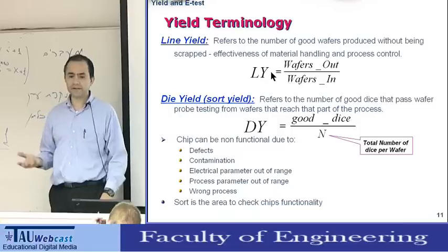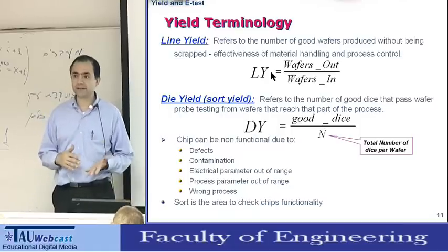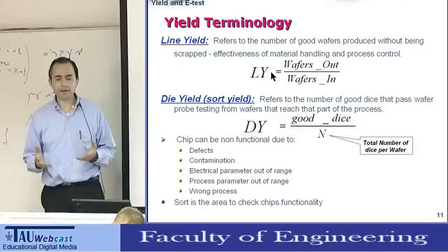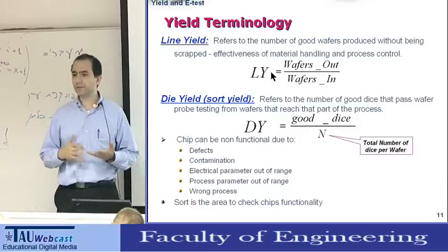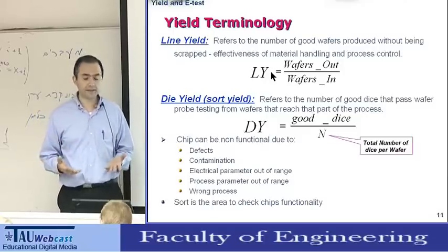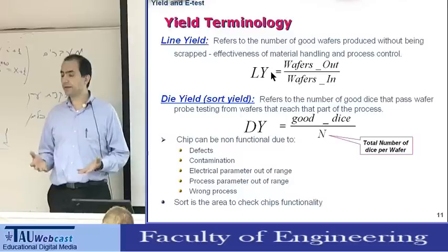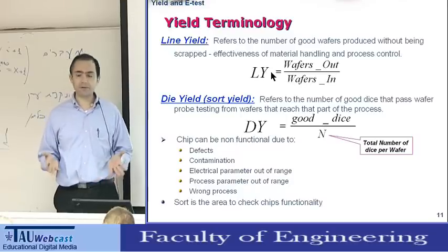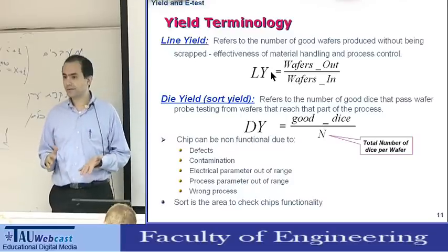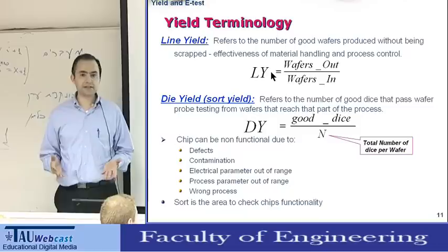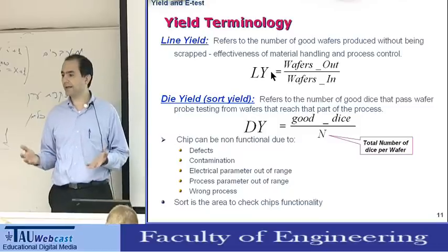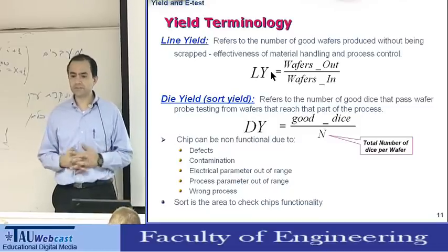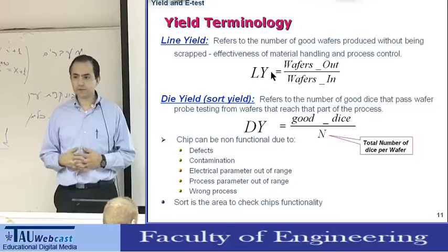The wafers out could be 97% of the wafers in, okay, 95%, 99%. It depends on the quality of the fab, the performance of the fabrication facility, and it also depends on the complexity of the process. A process with very few layers in an old technology is expected to have a very high line yield, about 99%. Wafer with the new technology...